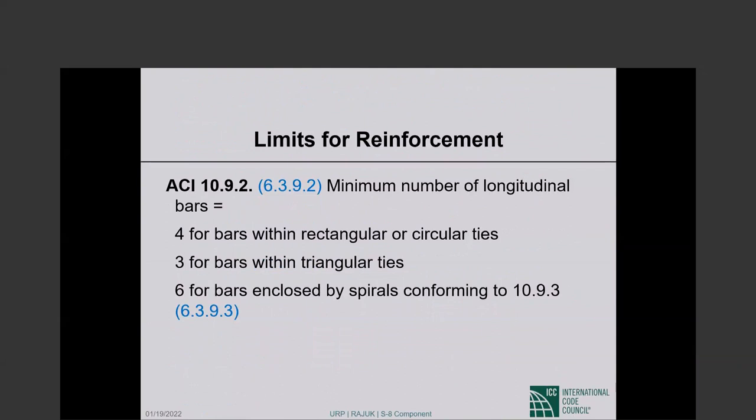The best columns are the columns with 1.5% reinforcement, something like that. They are ductile. They are good in every way. When you are pushing, going to 3-4% reinforcement, you are getting inferior structural members. You cram that much steel into a member, you are taking away from ductility. Also, reinforcement placement becomes a problem. Not so much the reinforcement placement, but placing the concrete after you place the reinforcement.